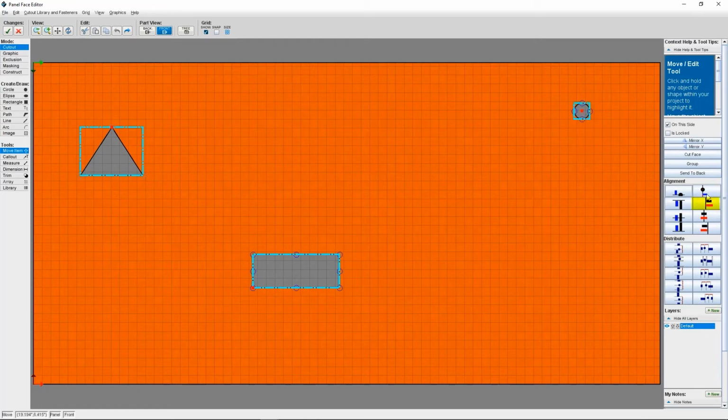Finally, if you're looking to precisely space cutouts or align them horizontally or vertically, align and distribute commands are your best bet. We've got a Proto Tech Tip on each of these functions. Check out the link below in the description. Basically, the align and distribute tools allow you to move 2 or more cutouts in specific ways based on distributing the space between each object equally or aligning 2 objects based off an origin or an edge with respect to your first selected object. Let's go through a quick example.